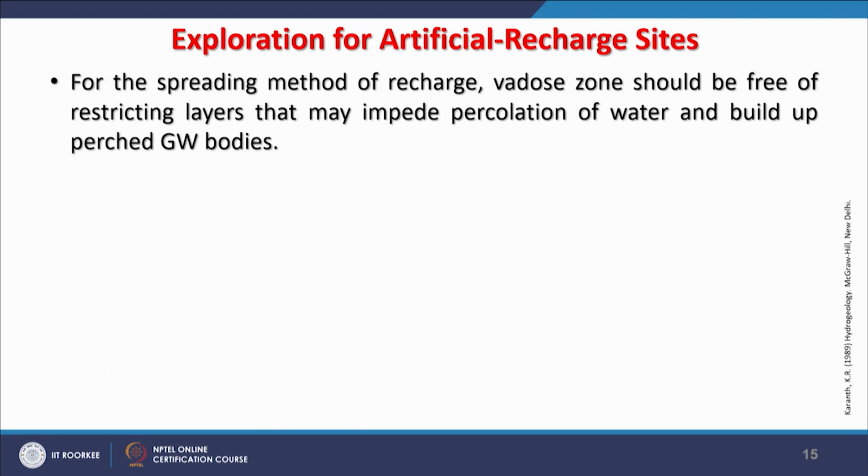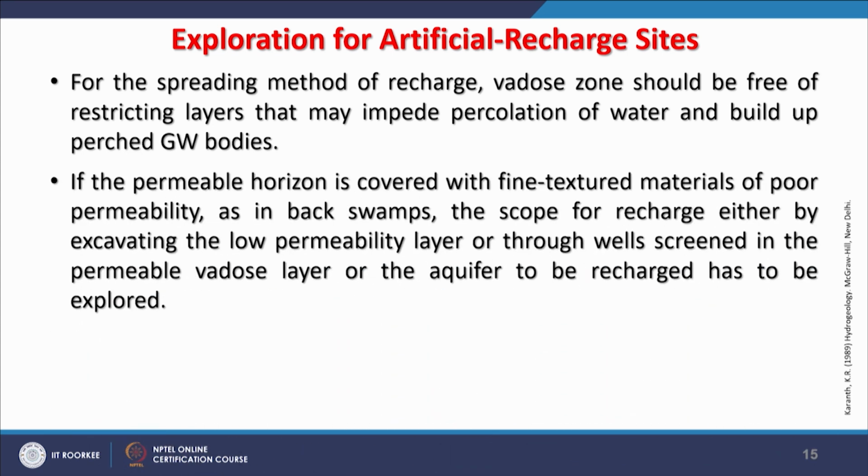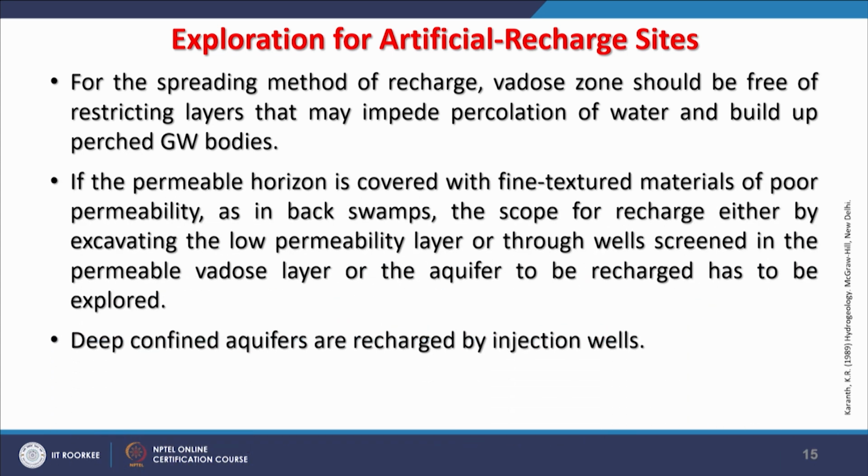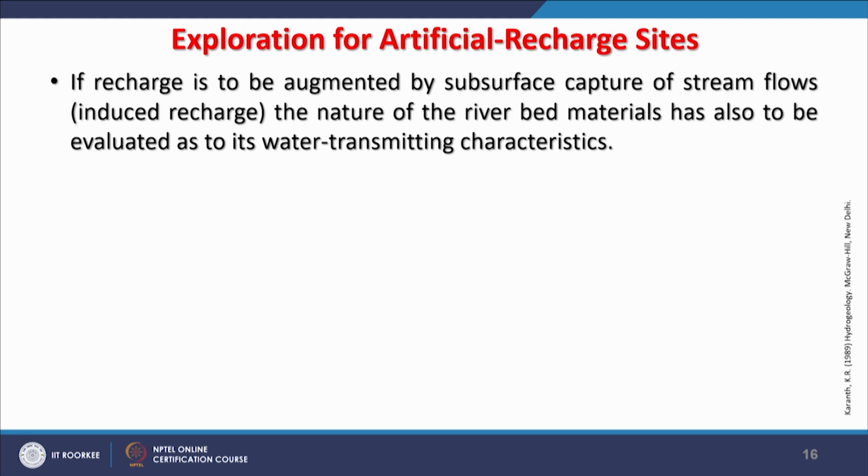Now, for a spreading method of recharge, this is done in permeable zones. If we want to augment recharge by subsurface capture of stream flows, and the example which I gave about Deoprayag, the subsurface capture of stream flows, which is also called induced recharge, the nature of riverbed materials has to be evaluated first, and its water transmitting capabilities or characteristics should also be considered.